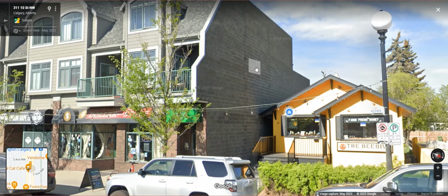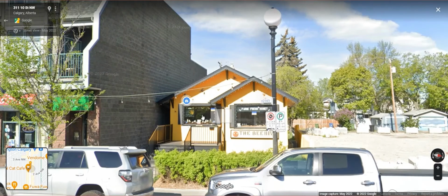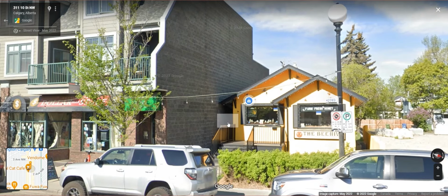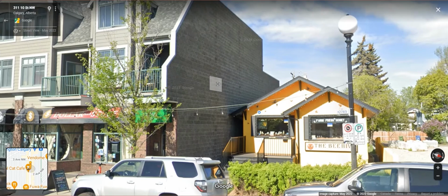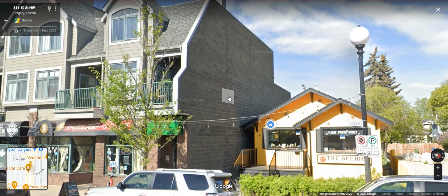Another reason would be that you want a maintenance-free wall, basically, because this is a good example. I mean, this house will get torn down probably someday, and another building will get built beside this, and you don't want finishes on there. They'd have to be non-combustible, but you wouldn't want to put non-combustible finishes on there that you have to maintain in some way. So if you had insulation and cladding and all this kind of stuff on there, and your air barrier and everything, you might have issues in the future doing maintenance on that or taking care of that. So, this is basically a maintenance-free wall being built here, that you don't have to worry about what happens next